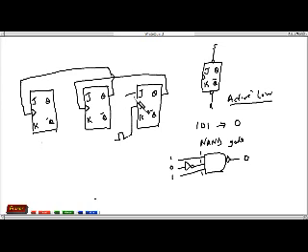Then all our JK inputs will be 1, just like in a mod 2 power n synchronous counter we designed before. Then all of them would have a reset pin. This is the reset pin for our flip-flops. And we make use of a NAND gate to reset the flip-flop as follows.